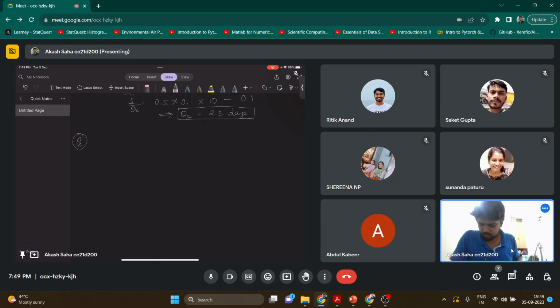So first we have to find out the effluent BOD, that is my SE. So what will be my SE? Simple direct formula. It is Ks (1 plus Kd theta c) divided by (theta c (Y K minus Kd) minus 1). Simply, we have derived this.